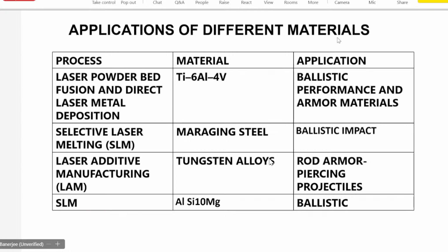So therefore thermal conductivity is changing, and the solidification time is changing. If that is there, then that creates the nano voids, and we may be ignoring it with an ordinary optical microscope. But for a particular use where I want very high precision, high safety, I will fail it. I will fail it because my design might be correct, but material processing has not been.